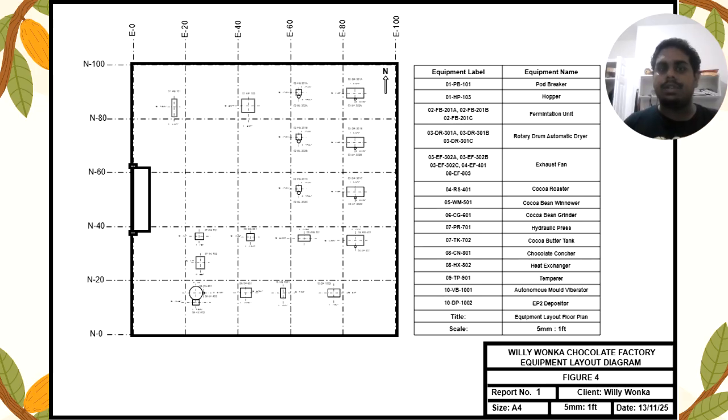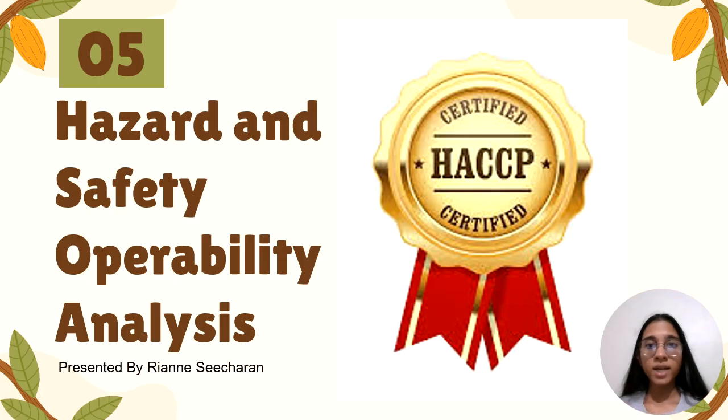To protect the safety of the equipment and all people involved, we conducted a hazard analysis, where we analyzed the causes, consequences, safeguards, and recommendations for no flow, higher temperatures, lower temperatures, and higher levels. In this presentation, we will analyze higher temperatures and higher levels.